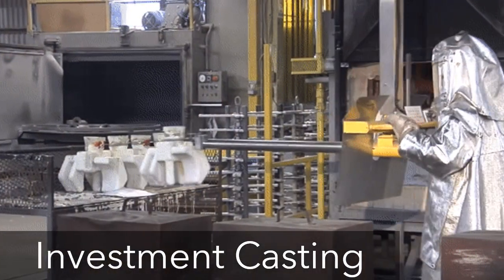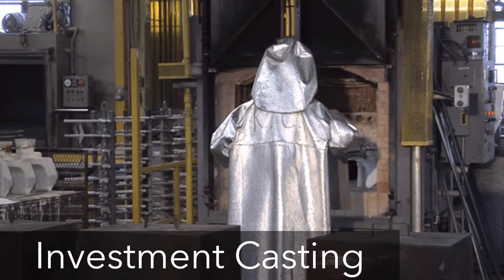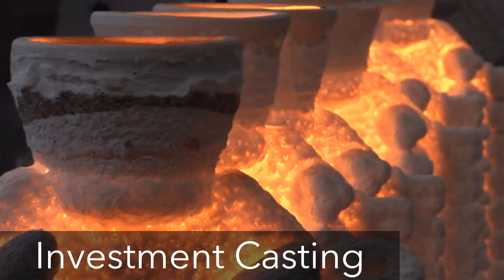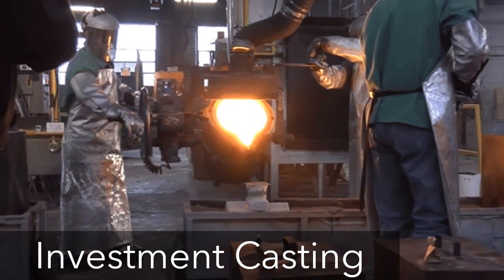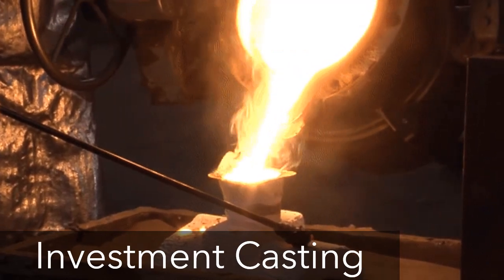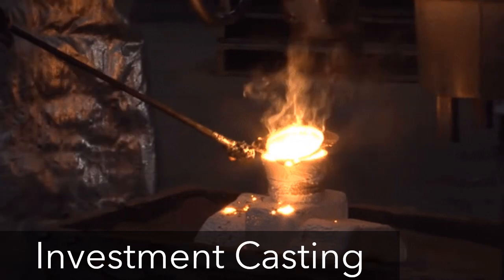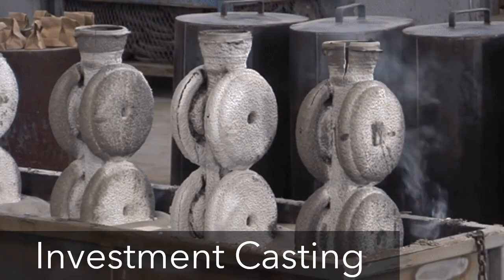The one-piece mold is dried in the air and heated to a temperature of 90 to 175 degrees. It's held in an inverted position for a few hours to melt the wax out. The mold is then fired to 650 to 1050 degrees for about 4 hours to drive off the water of crystallization and burn away any residual wax. After the metal has been poured and has solidified, the mold is broken up and the casting is removed.